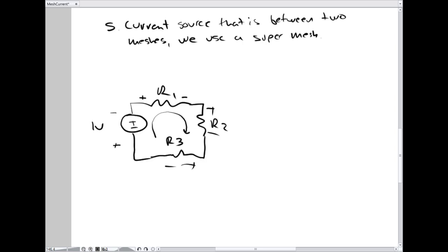So this brings about a certain rule that I like to follow, and many other people do as well: as you write down Kirchhoff's voltage law for mesh currents, if you encounter a voltage source, the sign you hit first is the sign you have to put in front of the term for that voltage source. Because for all the resistors, you hit the plus first.